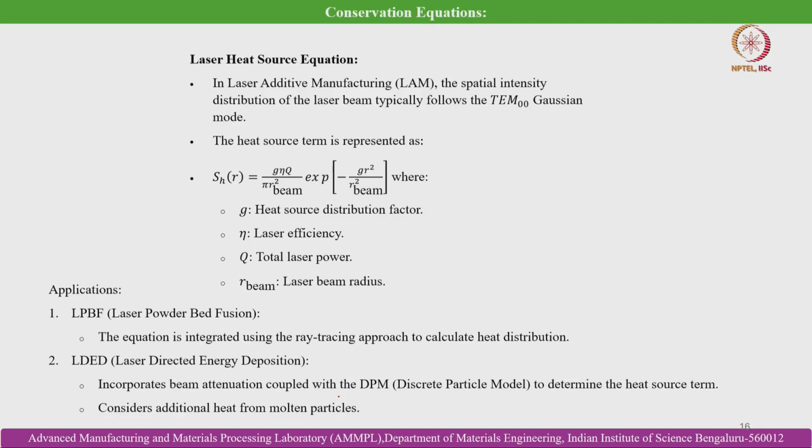Okay. So here comes the laser heat source equation. In laser additive manufacturing, the spatial intensity distribution of the laser beam typically follows the TEM00 Gaussian mode.